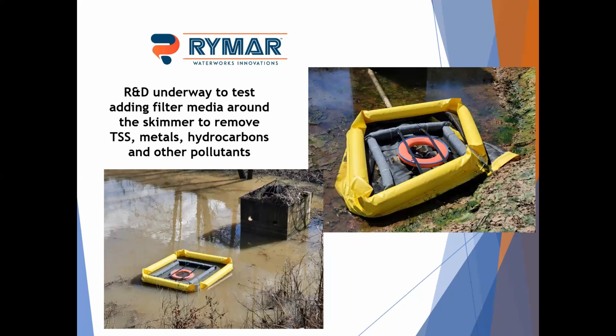The other advantage is 100% of the water from the water quality storm and below will go through the filter and get treated. Whereas, if you get a very small rain, say a 1/4 inch, and it hadn't rained in a week, that typically has no settling time, so it flows straight through your pond.